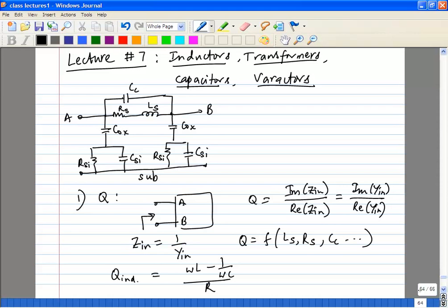Actually, you are going to ground this metal shield. If you want a good shield, you have to ground it very well, which means even if you use M5, you have to ground that M5 very well, which means any metal layer below it, you don't care what happens to it.